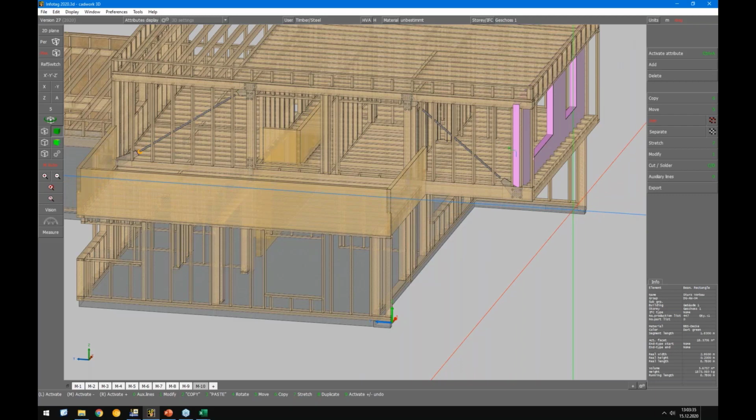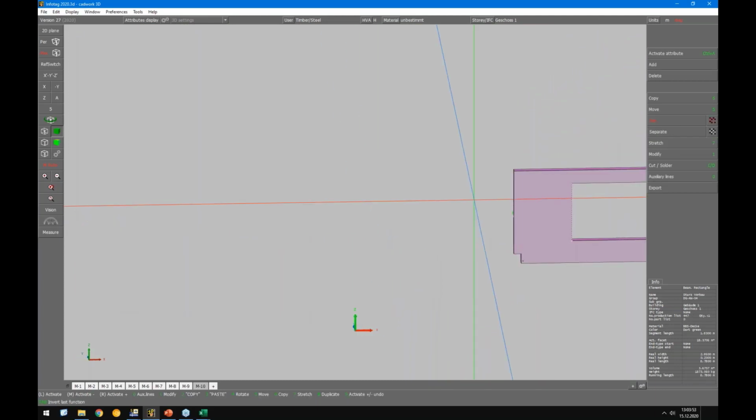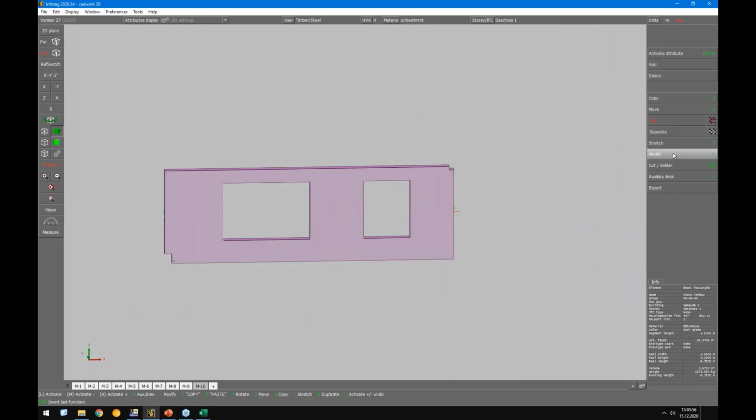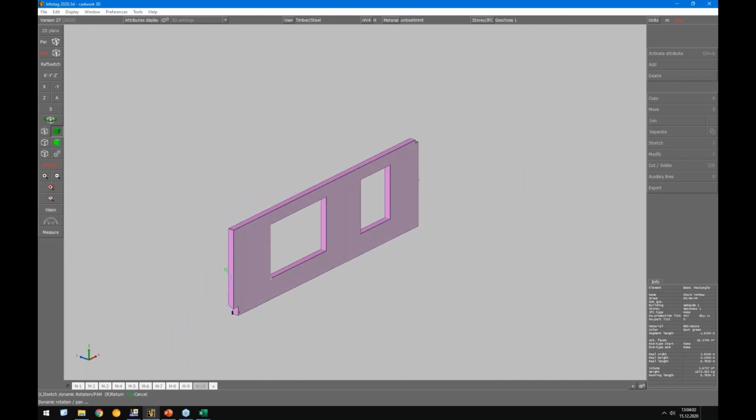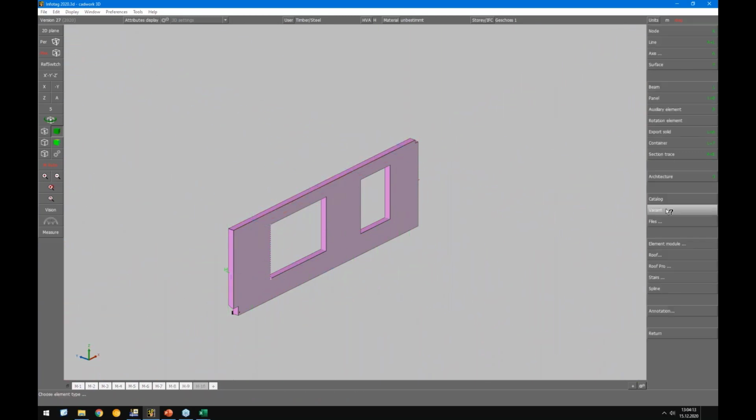The aim now is RFEM, and we can use it by exporting, for example, an IFC file, or we can export a DXF file. But there's one smarter solution. In this case, I will have a look only at this element here, and I'm interested in the center lines, because this is a solid element, and of course I want to design it with a surface element and not with a solid element. So therefore we need the center lines. And here I can use a variant from CADWork.